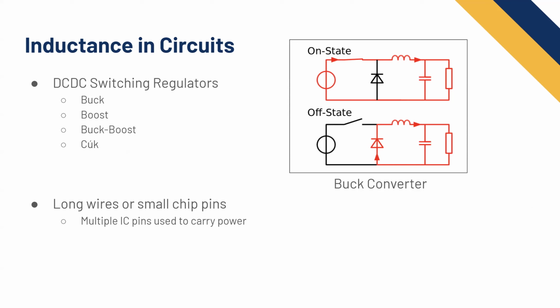I can go through more examples of different types of voltage regulators. I think I had to cut that lecture out because we're doing other stuff this semester, but we can do an extra session if people want to see that. There's a whole bunch of different ways you could do it. There are some diodes that have a reverse voltage blocking, so what if we did a resistor and then we just reference the reverse voltage of that diode, or we can do switching regulators.